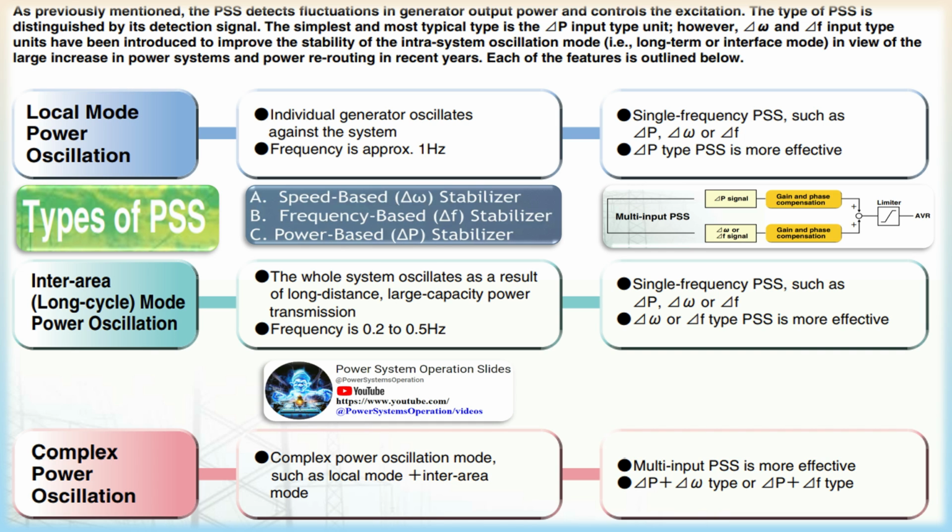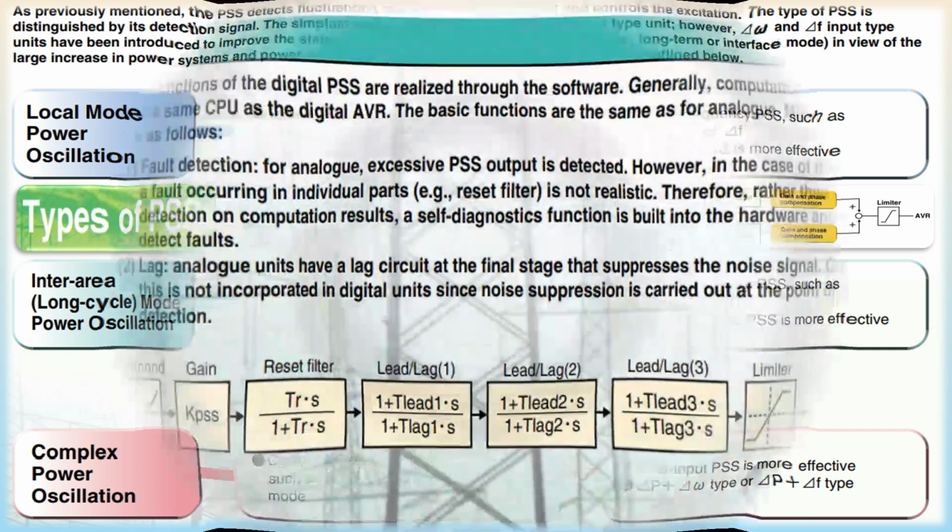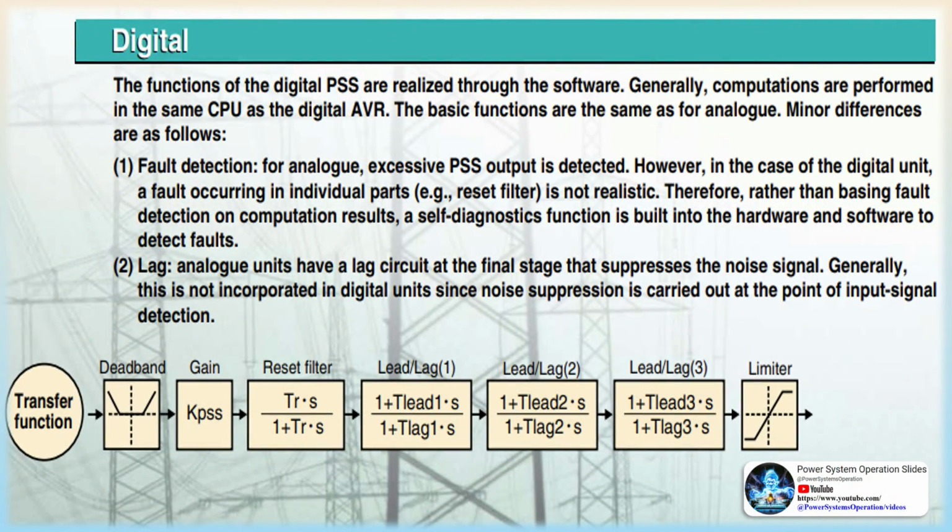A power system stabilizer (PSS) is a control system installed on a generation unit that monitors variables such as current, voltage, and shaft speed. When necessary, it then sends the appropriate control signals to the voltage regulator to damp system oscillations so that frequency does not stray beyond tolerances.